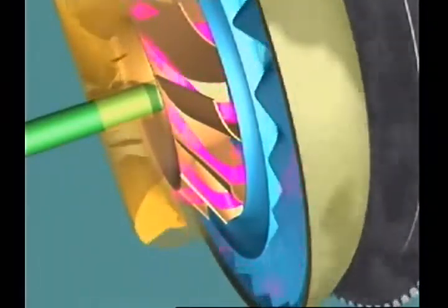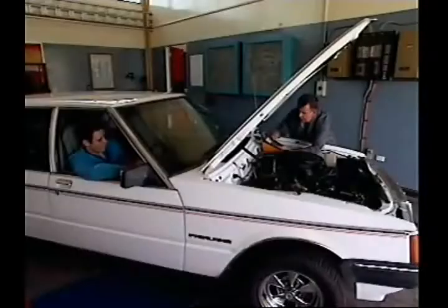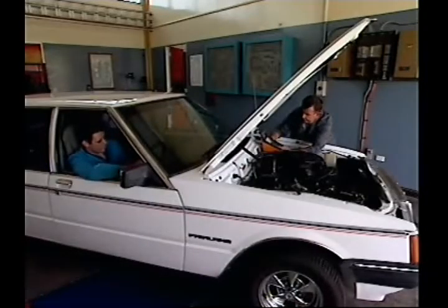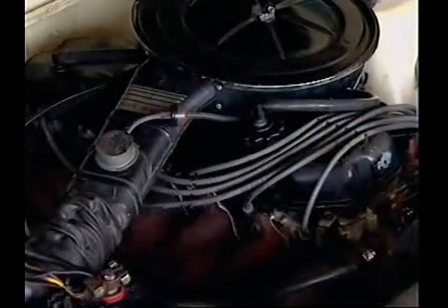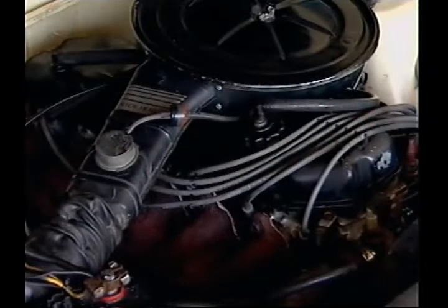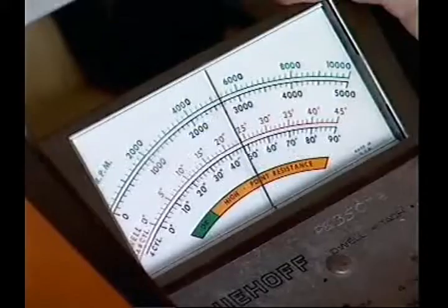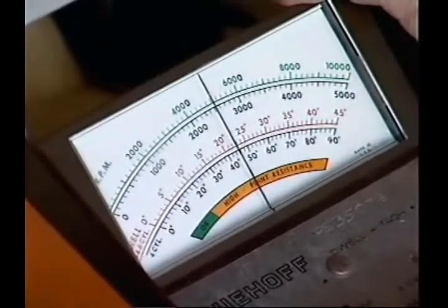Torque multiplication exists only when there is a difference in speed between the impeller and the turbine. The magnitude of torque multiplication depends on load. When the turbine is stalled, it has a maximum value of about 2.2 to 1. Stall is an operating condition where the turbine is stationary and the engine throttle is wide open, making the rotational speed of the impeller as high as possible.